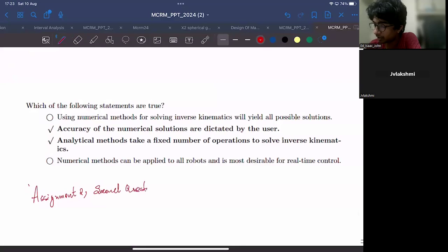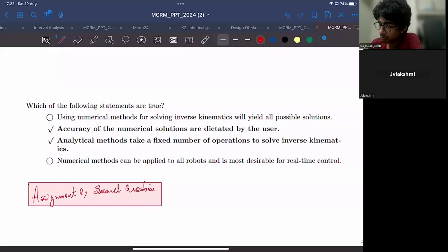Okay, we'll review this. And again, in the third question also, in the discussion, we thought that in a prismatic joint, what are the constant kinematic parameters? We thought that the 3 parameters are constant, but here the answer is only 1 parameter. That is the link twist is the right answer. But we kept link twist, link length is also constant, joint angle we discussed, constant, sir. I kept the same thing, but answer is link twist, the last one, sir. Third question. That is not correct. In that joint, the only variable is the joint distance. Everything else should be constant.